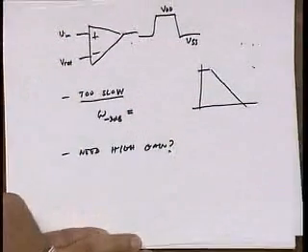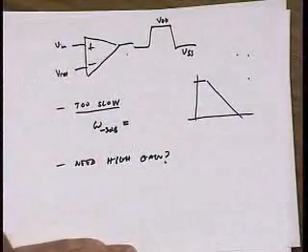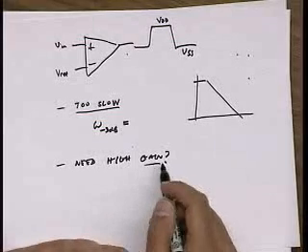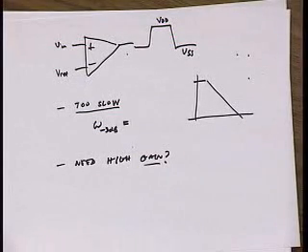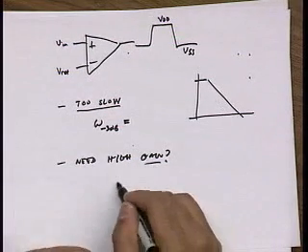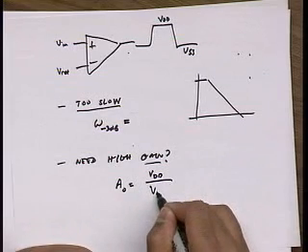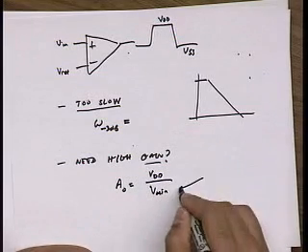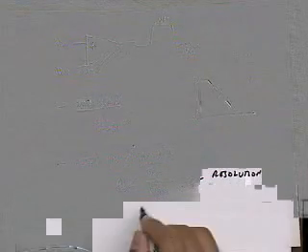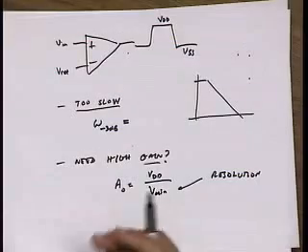Well, then I need a gain of 1,000, right? So yeah, I may need high gain. If I want to resolve 10 microvolts, I'm going to need more gain, right? So the gain requirement is determined by VDD over Vmin, which is kind of the resolution, right? So the more resolution I want, the higher the gain.